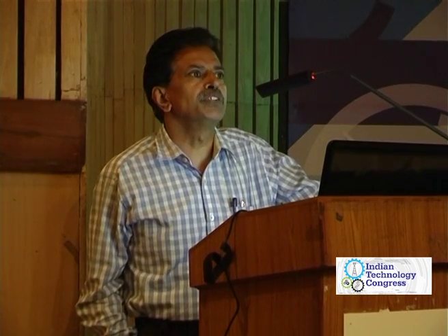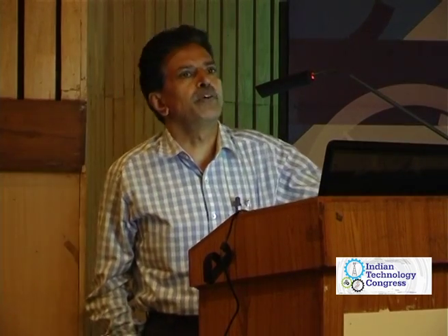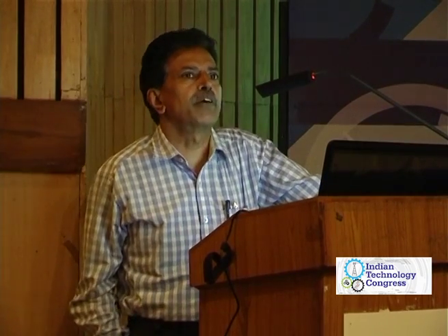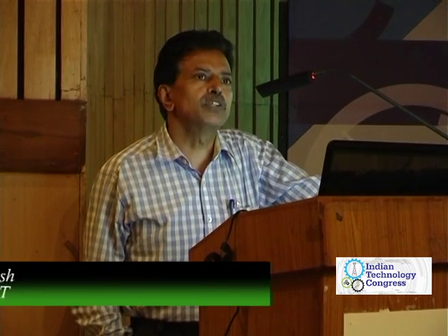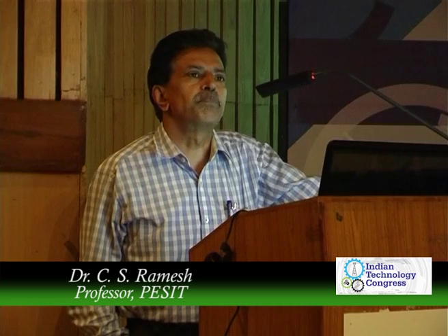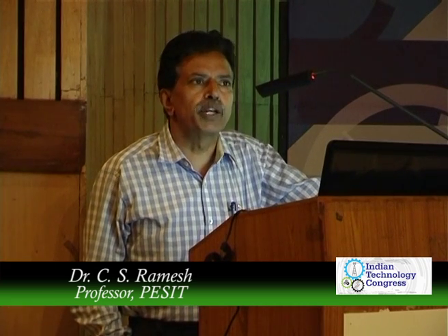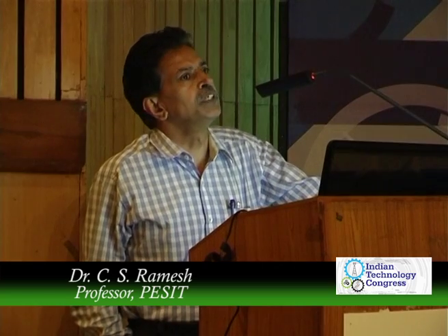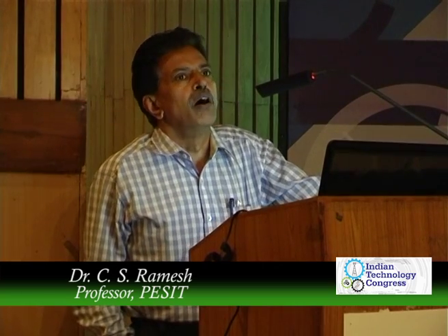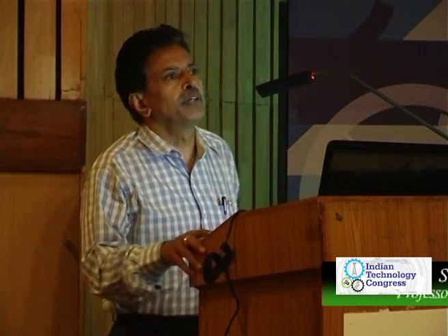I think most of us need to pick up some of the physical properties of the reinforcement together with the matrix materials that are available and being studied. We need to do a lot of groundwork before we decide the appropriate reinforcement. For example, if you're looking at silicon carbide, the most widely used, what happens with the CTE of a piston? And there is oil compatibility, so that's another issue.